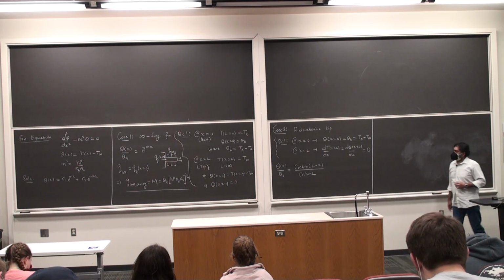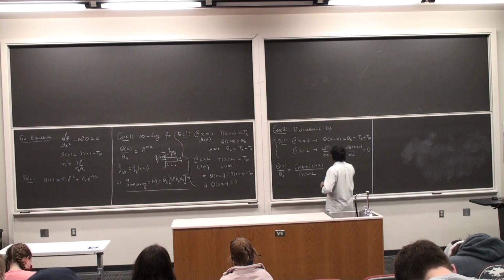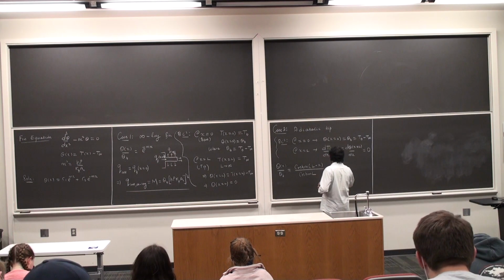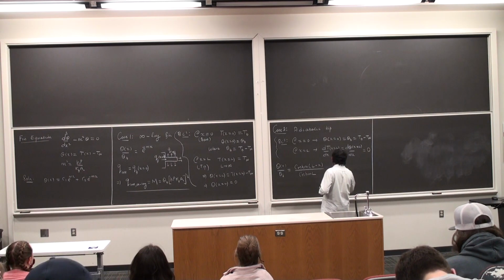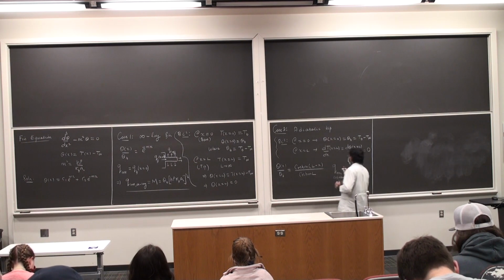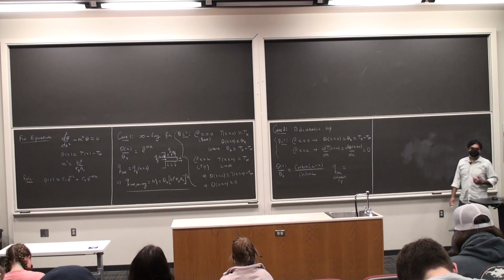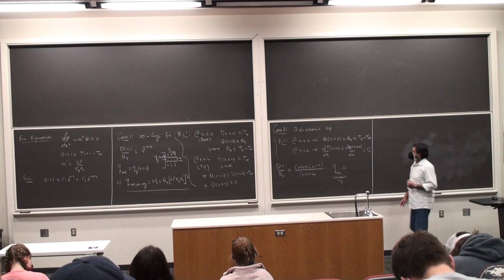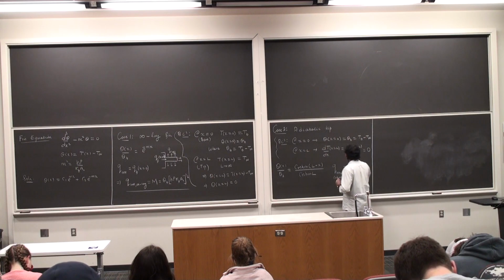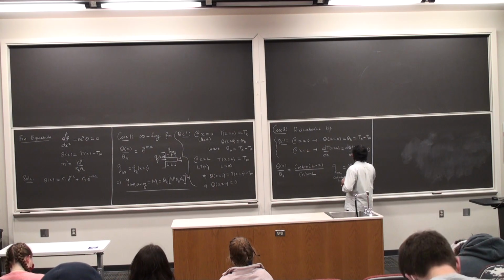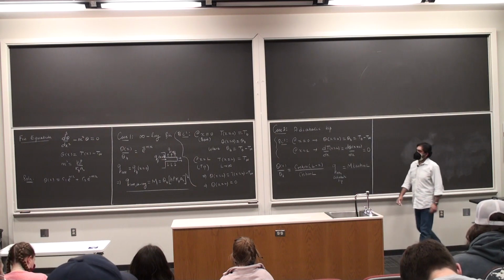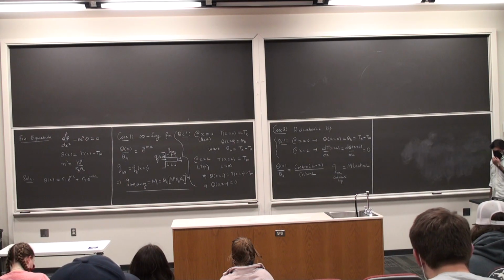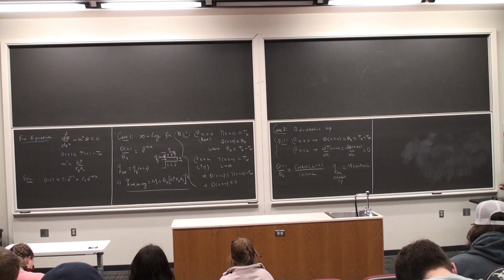And then the heat loss rate, Q loss, adiabatic tip, is just the derivative of this entire thing, and we will not be doing it, of course. We did it last time, M times tanh m L. This is the second case.